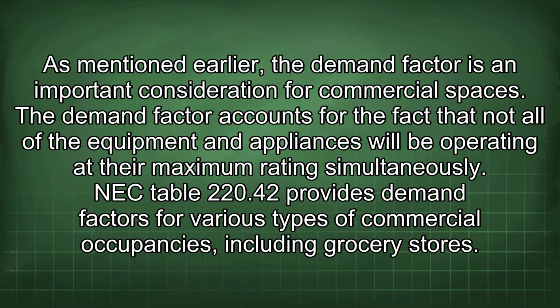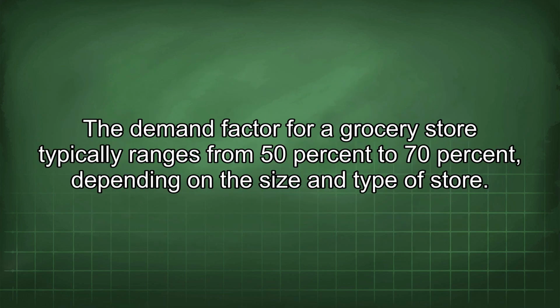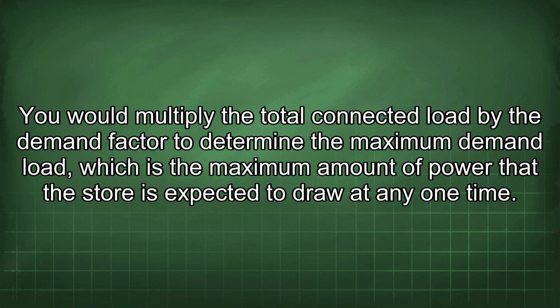As mentioned earlier, the demand factor is an important consideration for commercial spaces. The demand factor accounts for the fact that not all of the equipment and appliances will be operating at their maximum rating simultaneously. NEC Table 220.42 provides demand factors for various types of commercial occupancies, including grocery stores. The demand factor for a grocery store typically ranges from 50% to 70% depending on the size and type of store. You would multiply the total connected load by the demand factor to determine the maximum demand load, which is the maximum amount of power that the store is expected to draw at any one time.